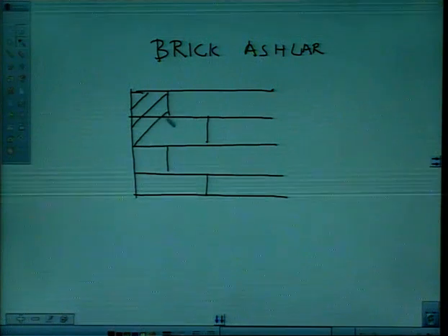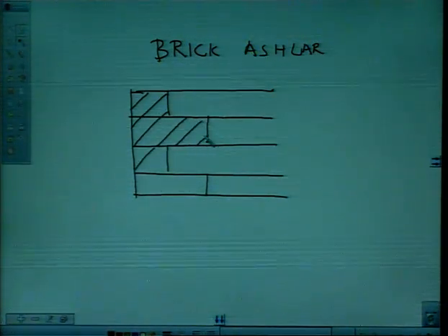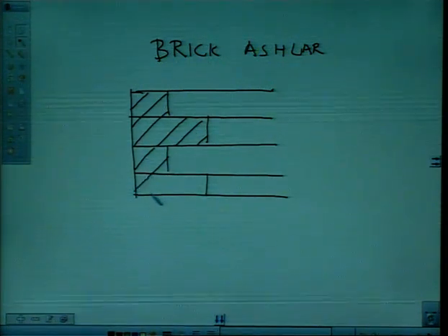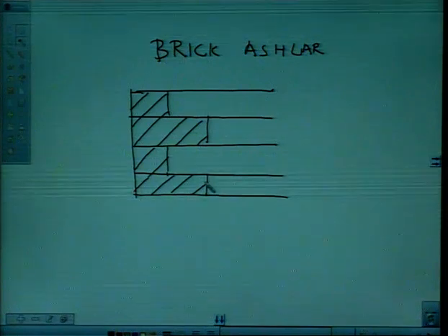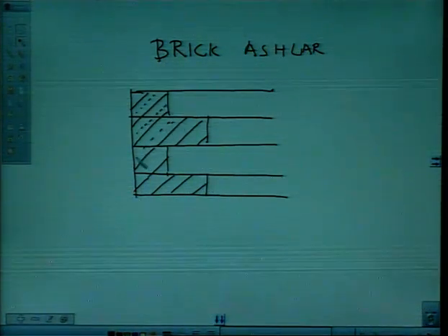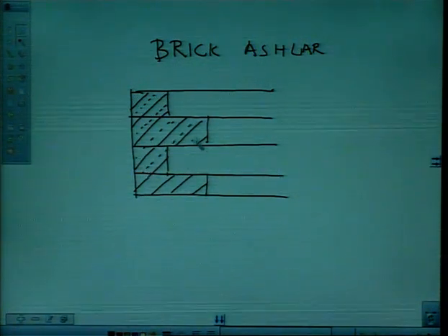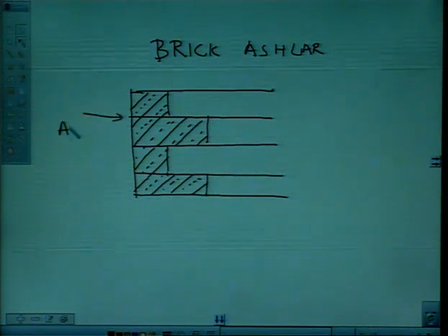Because these stones are used on the face of the building, they should look very well dressed. So, fine dressing is done, two-line or three-line dressing should be done for these ashlar stones, so that it gives a better appearance to the building. So, this is my ashlar face.